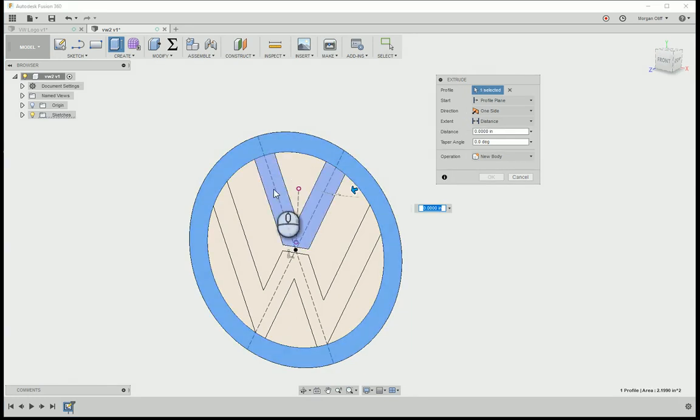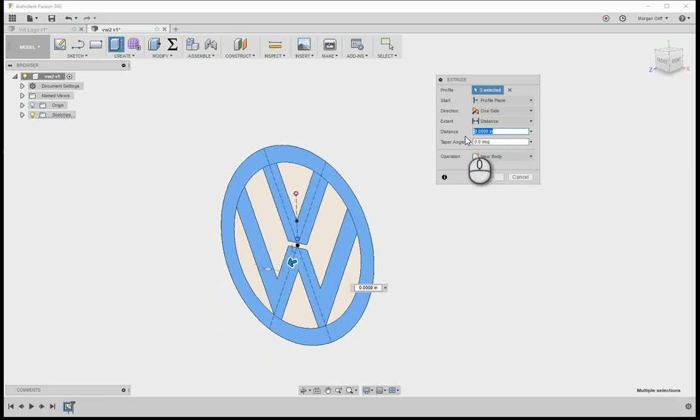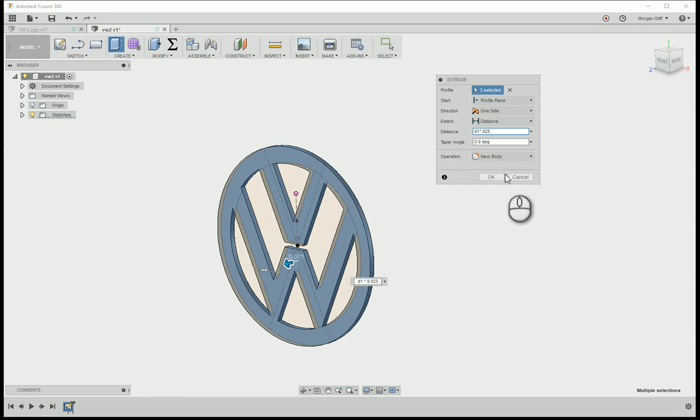So we've got a solid model if we select all of the correct things. And actually, the distance I want to be kind of proportional, because I don't want to just say that it's an 1/8 inch thick, because if I make a 24-inch one, maybe I don't want it to be 1/8 of an inch thick, or if I go down to one that's only an inch in diameter, I don't want that to be 1/8 of an inch thick. It may be something proportional. So what I'll say is D1, which is our original diameter, times 0.025, the same as the gap in the middle. That looks kind of nice and proportionate, right?